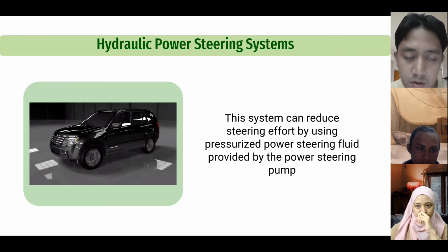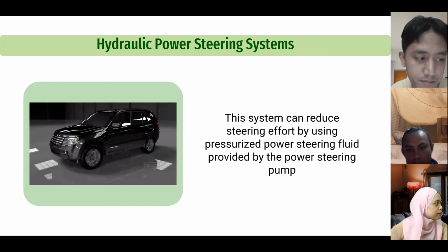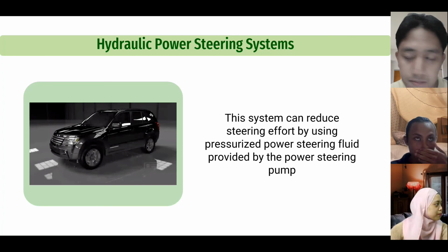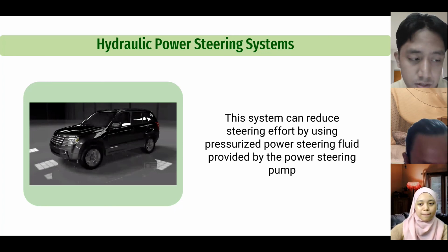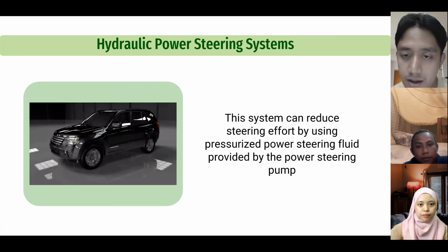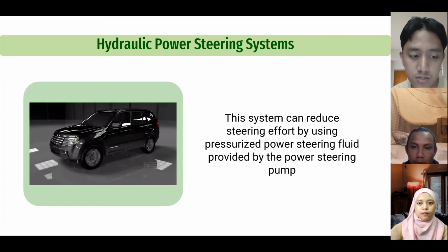Okay, now I will explain about the hydraulic power steering system. The hydraulic power steering system can reduce steering effort by using pressurized power steering fluid provided by the power steering pump. An engine driven accessory drive or serpentine belt activates the pump and directs high pressure power steering fluid to the input side of the power steering gear control valve through the high pressure hose.